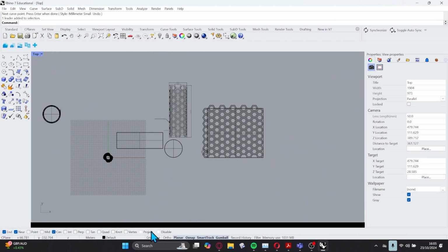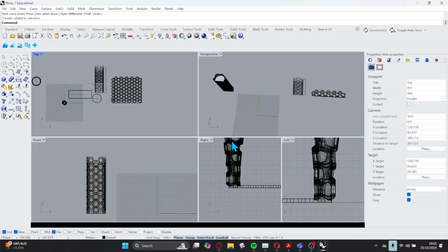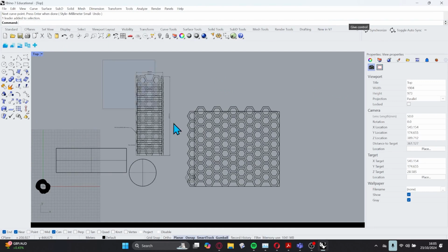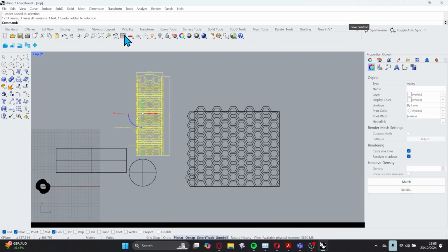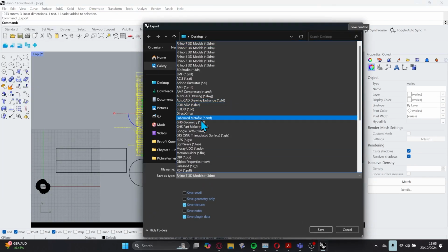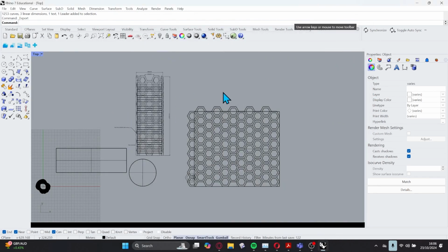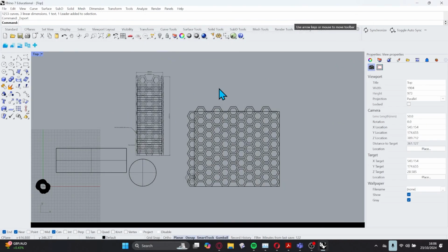It does. I guess the only follow-up is, when you're exporting that, how do you do it without just exporting everything on the page? Like DWG or PDF. So check this out. If I go to the top view, let's say I want to select that, and I go to File, Export Selected. I can now export this as a DWG file. Let's say, for example, I do all my drawings in Rhino. So I do all of my annotations, my drawings. When I do an architectural job, I do them all in Rhino.